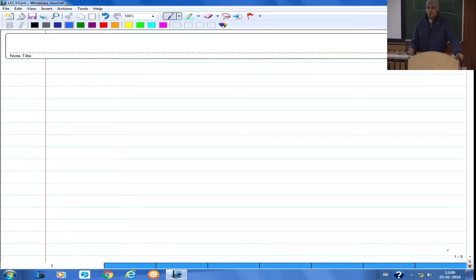And also of course the generalized force, the internal forces at the different nodes. In the case of 2 noded elements it was an assembly, so we had some internal force at the left, some at the intermediate and some at the end. Whereas in the case of the 3 noded quadratic element we had internal forces only at the boundary nodes, the starting node and end node. At the intermediate node, because it is internal, there is no cut section there, so no internal force is shown. So that was the question. That's the situation always when you compare linear and quadratic elements.